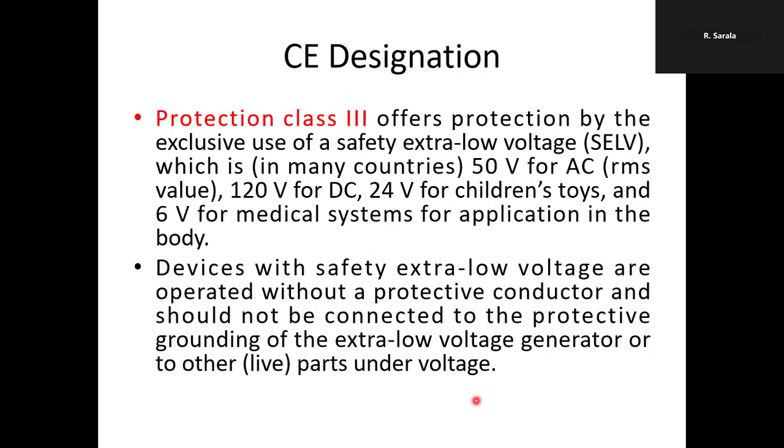This class provides protection against extra low voltages, that is, safety extra low voltages. In many countries this represents 50 volts for AC, 120 volts for DC, 24 volts for children's toys, and 6 volts for medical systems for applications in the body. Devices with safety extra low voltages are operated without a protective conductor and should not be connected to the protective grounding. Then the extra low voltage generator or other parts may get damaged.